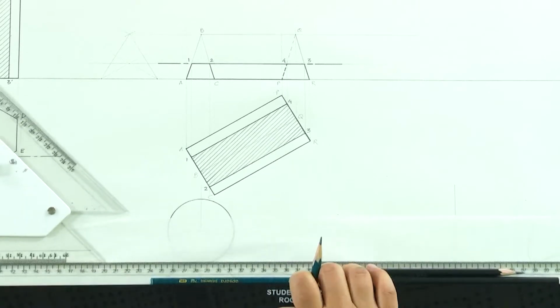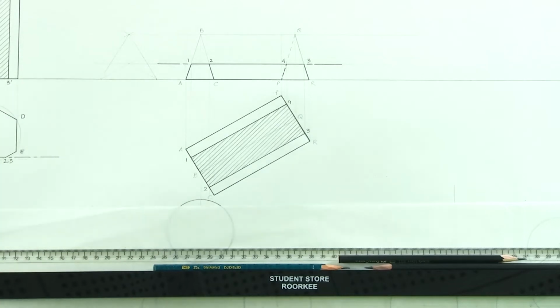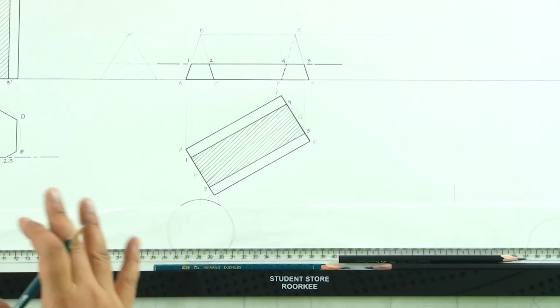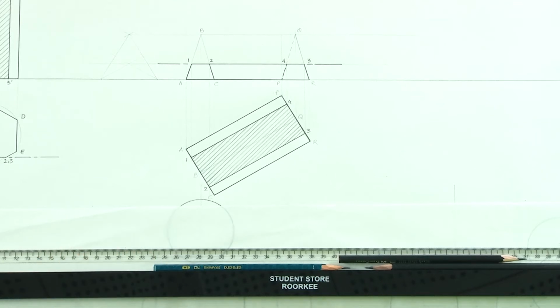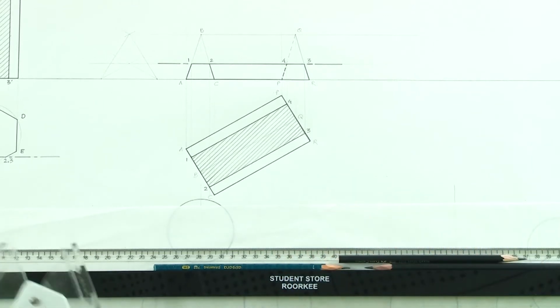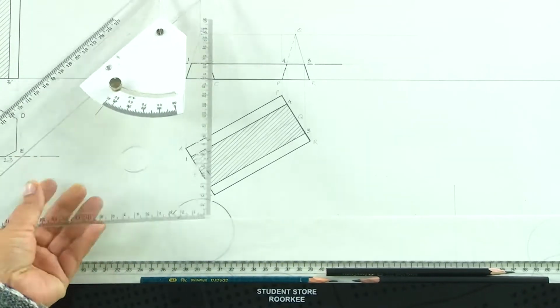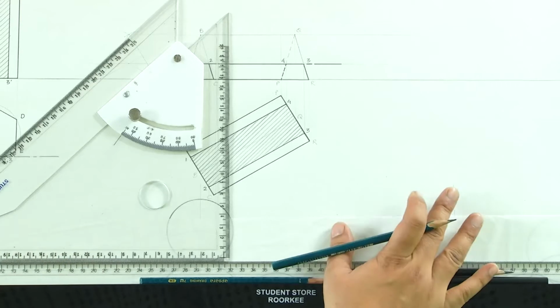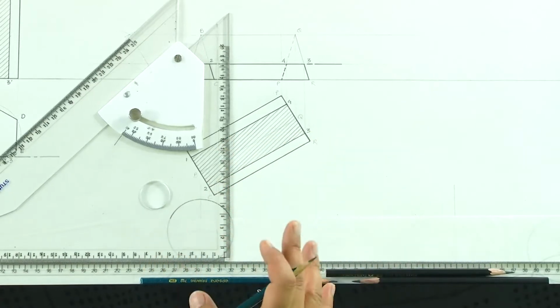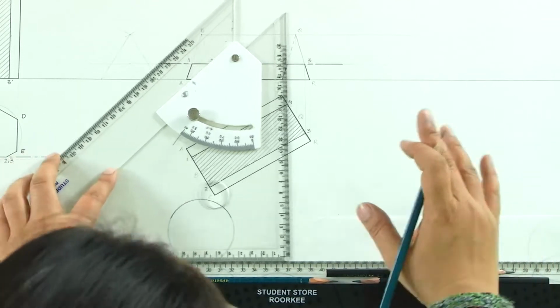Now, we could get it in one single step simply because in both these cases the section plane was parallel to one of the reference planes. Now, what happens if we have a section plane which is inclined to one of the planes and perpendicular to the other? So, here again I will take the example of a simple rectangular prism, where the base is a rectangle and it is kept perpendicular to HP, but the side of the base is inclined to VP.